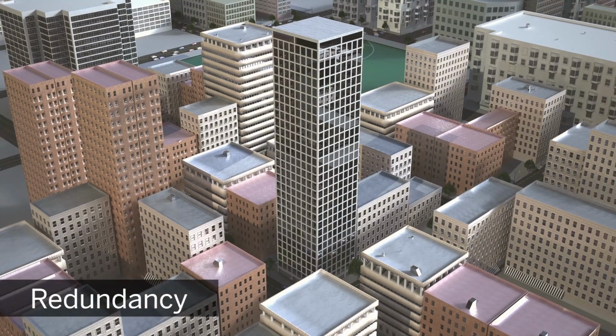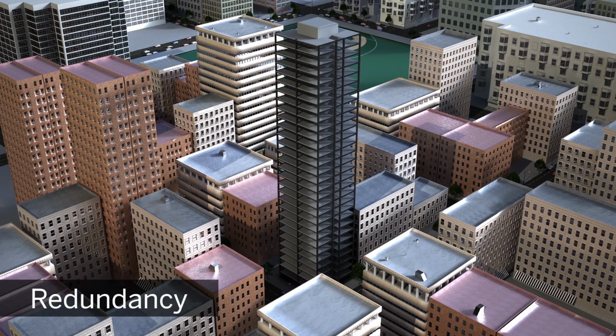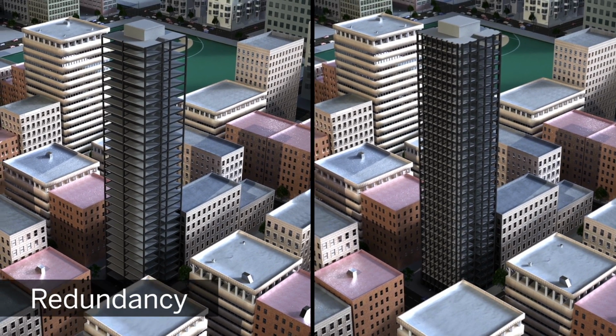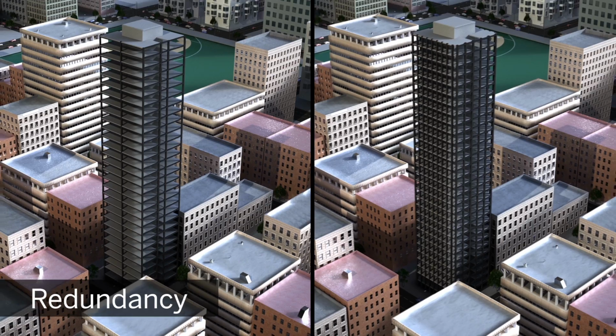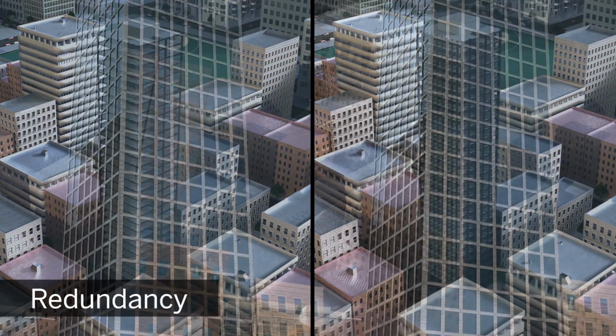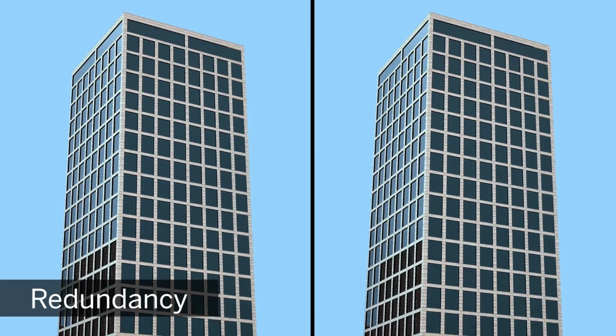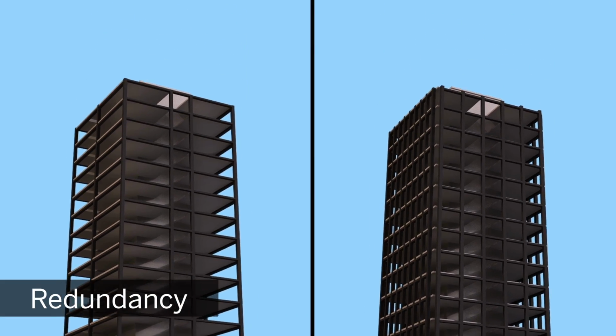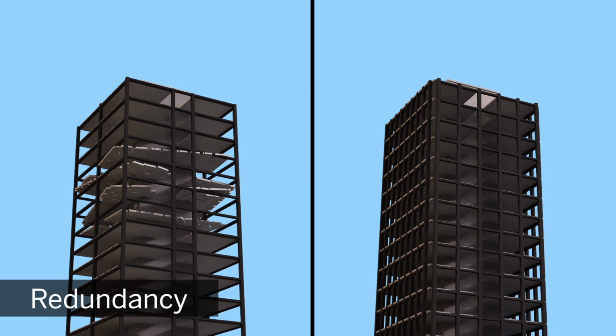If all of a structure's strength and resistance is concentrated in only one or a few elements, the structure will not have the necessary residual strength if these elements are seriously damaged, and it could collapse. If a structure is redundant, a relatively large number of elements participate in providing a structure's strength, and if only a few are badly damaged, the remaining elements should have adequate residual strength to prevent collapse.